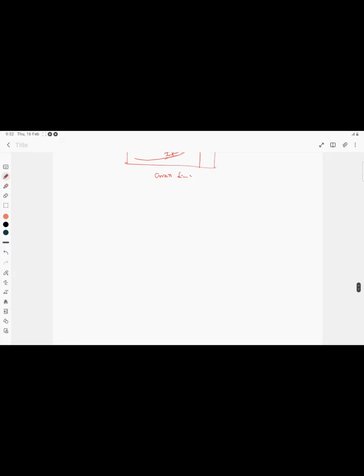And there is another relation with respect to the crack length and grain size. Grain size is taken in the x-axis and the crack length in the y-axis. So this is how it goes. If the grain size is lower, the crack length is lesser. This is observed in two kinds of materials, one with high boron content, another with low boron content.